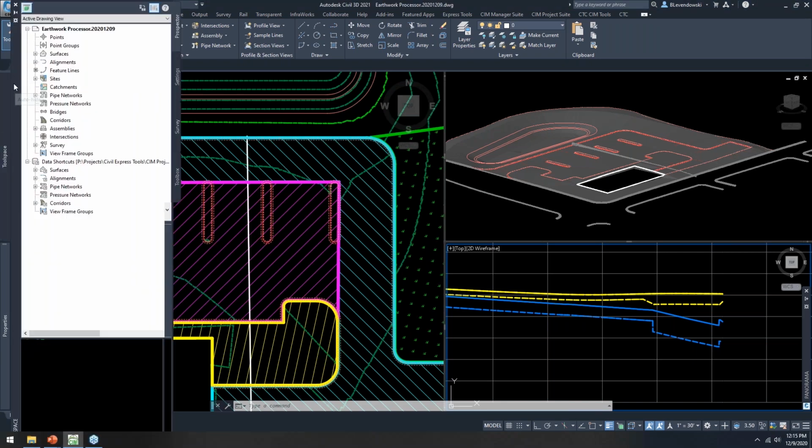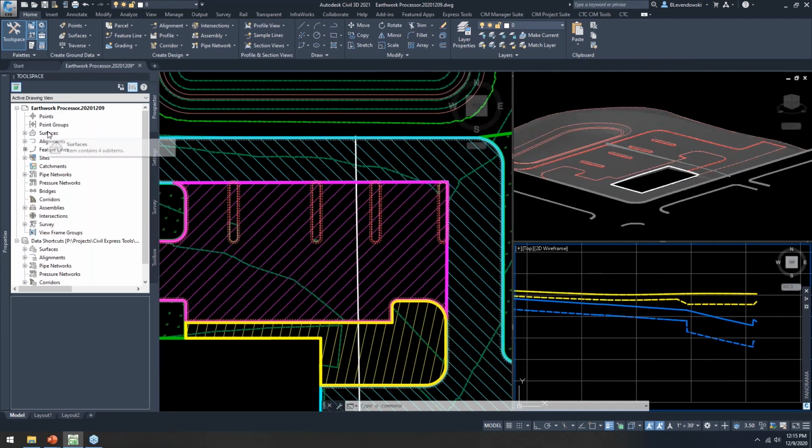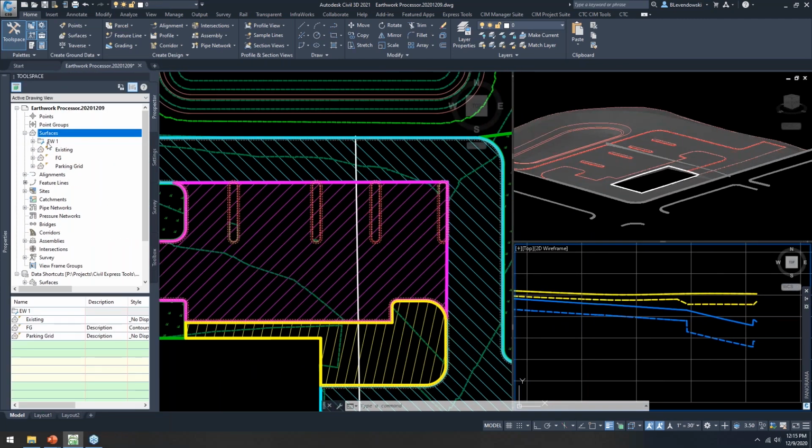If we want to understand a little more what's happening behind the scenes, let me briefly explain that. Now I told you we're not doing anything proprietary. There's no special CTC object we're creating. All we're doing is creating surfaces, adding break lines to them to get subgrade surfaces and stripping surfaces from which the tool then calculates your earthwork volumes.